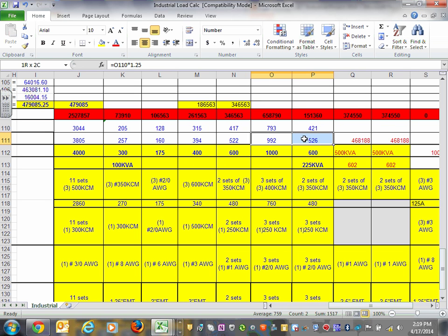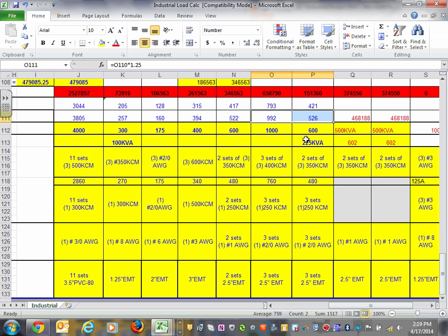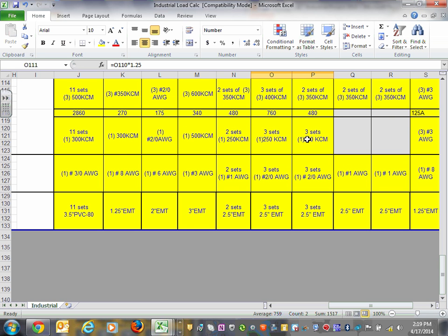My bus duct, I don't know if I have that one. Yeah. When I size for the bus duct size, guys, and for the actual panel size, and for the disconnect, this is my Bible. DeWalt, has anybody seen that? That's the new ugly. Yeah, I like it because I know the circuit breaker size from an NEC code book, but I don't know how they size the panels. Do they have a 350 amp panel, or do you jump to a 400 amp panel? So this will give you the actual size of the panel for the most part. $18, we can buy it.